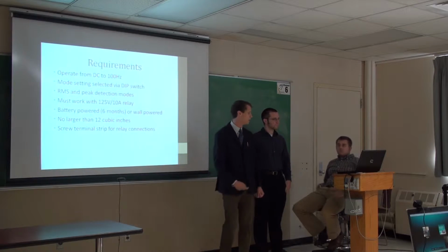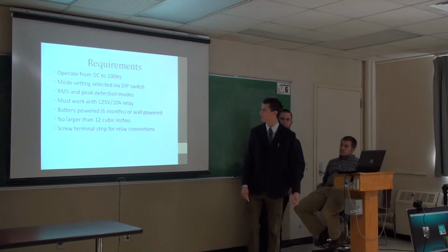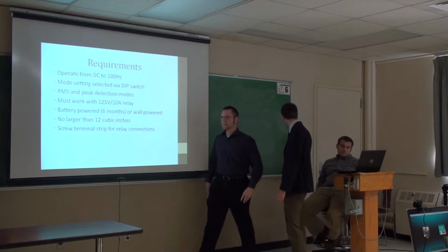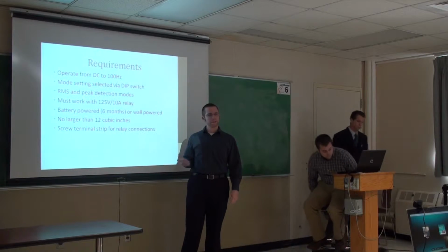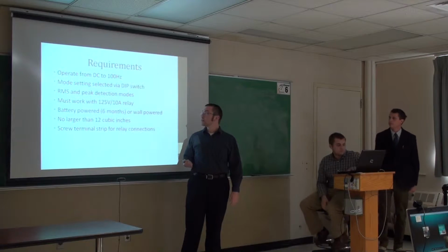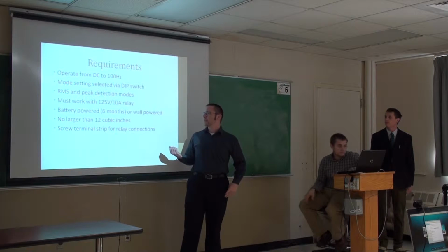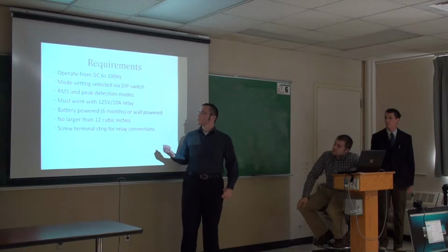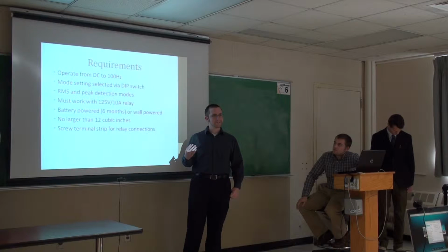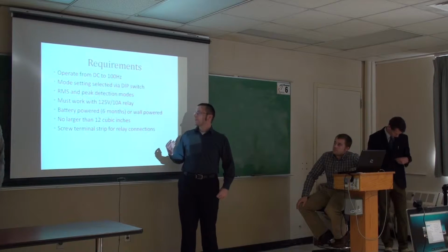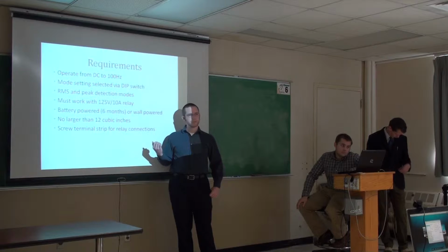And now, take it over to Tom, and we'll talk about the problem requirements. Hey guys, I'm Tom, and here are some of the project requirements given to us by Greg at IST. As you can see, we need to operate from DC to 100 Hertz. We need to be able to set the G-force levels using a dip switch. We need to set the levels that we're going to detect on our device. And we also have to be able to choose between RMS and peak detection modes.